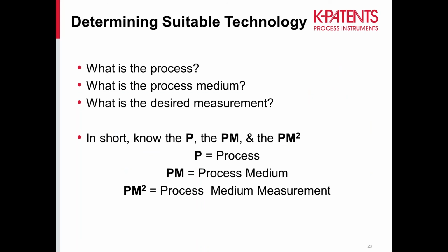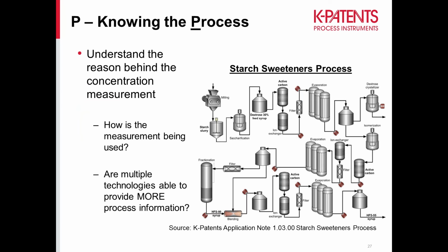Anytime you're putting water in or taking water out of a solution is a perfect example or application for a refractometer. In this particular case, the inlet of the evaporation process is very good to know, because now you know the concentration of the liquid material coming into the evaporator. So what you can do is then monitor that feed forward and control the amount of steam that's needed to boil off the liquid. If you know what's coming into the process, then you can control your steam and save on energy costs.